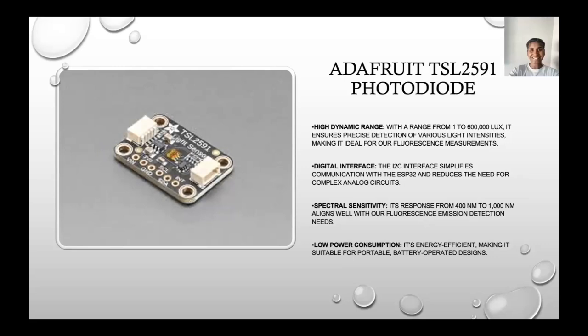Also having that digital interface is very important, with the I2C interface going hand in hand with the communication of the ESP32 microcontroller. And then it also has low power consumption. All the devices that we try to have have this, and we wanted to make sure that we weren't overheating our device, so we chose something that had low power consumption.